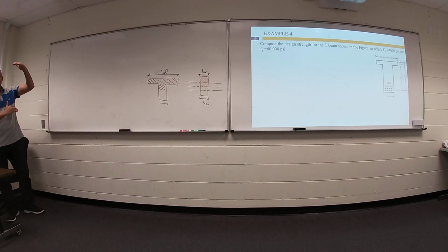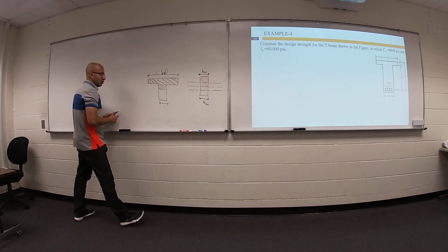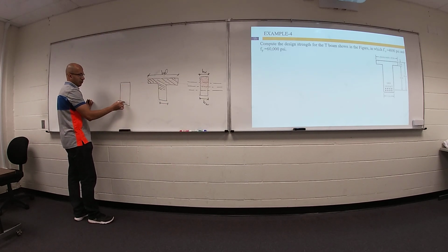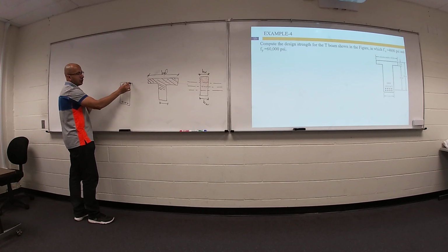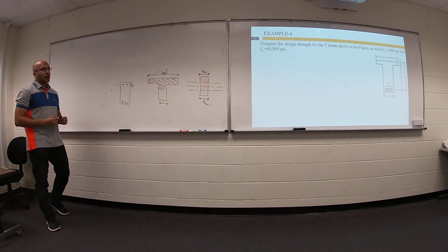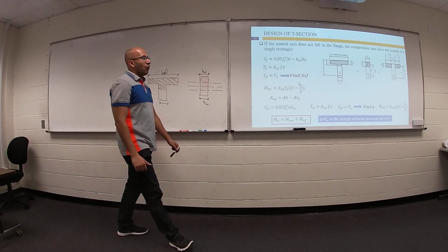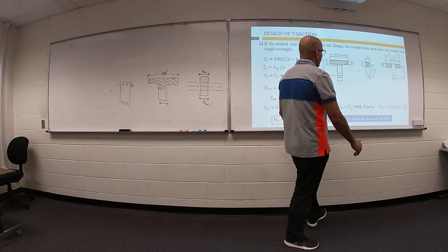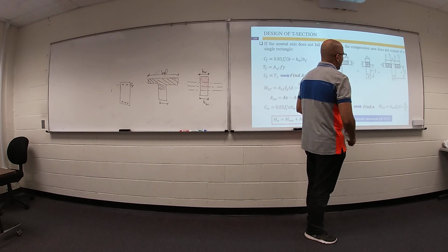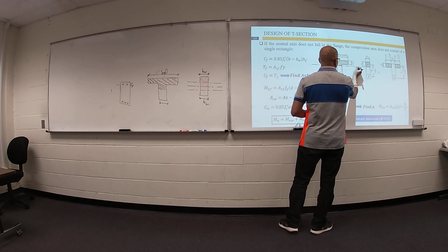If we have a double reinforced section, we have two options. Do you remember? No? Yeah, assume your steel here is yielded, and do your calculation and check if this steel yielded or not. If not, we need to repeat. If yes, that's okay, keep going. Anyway, so we need to do another calculation where your neutral axis is within the web.